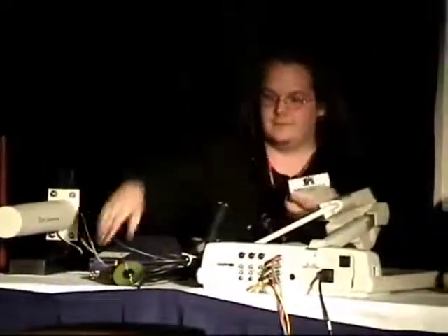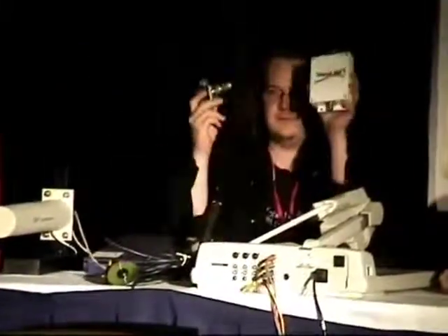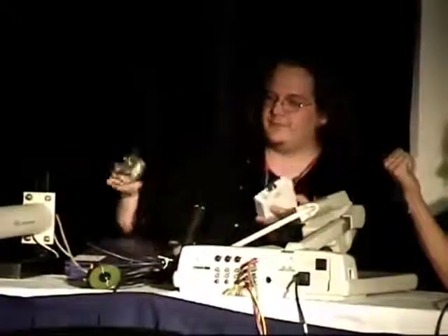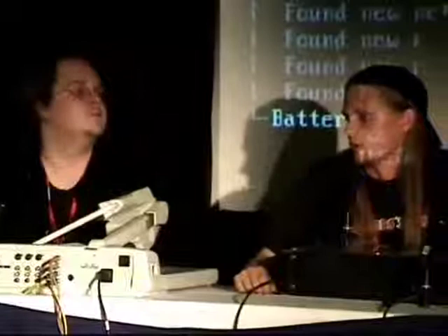Also related to antennas, we have an amplifier here. This is specifically a 500 milliwatt amplifier. It comes in 2 pieces, a power injector and the actual amp itself. It will increase your transmit power by 500 milliwatts. Of course, you can get them up to, the largest one I ever saw was for 100 watts. The largest one you're ever going to be able to buy was 1 watt.